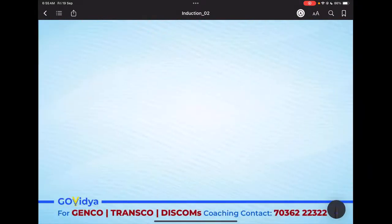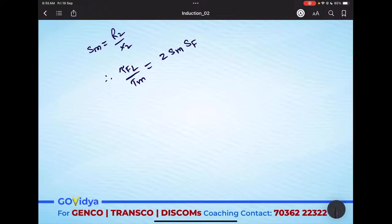We know that at maximum torque, slip will be R2 by X2. Therefore, full load torque to maximum torque ratio can be given as 2 into SM and SFL divided by SM square plus SFL square, where SFL is the full load slip.